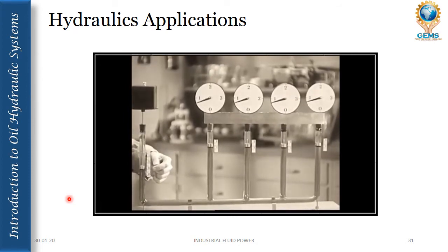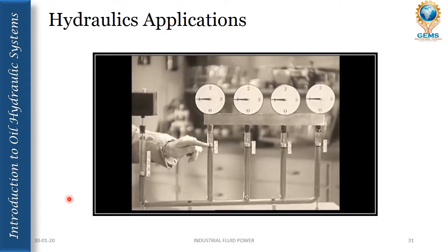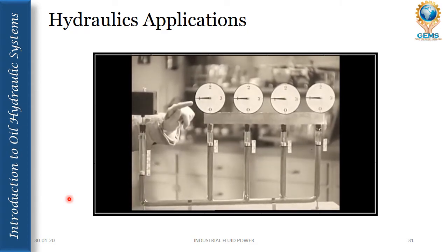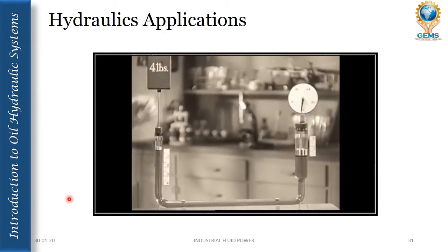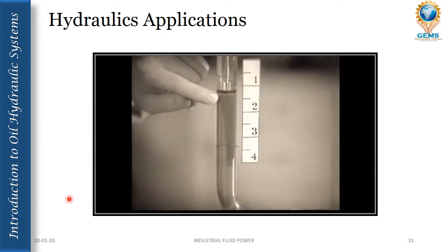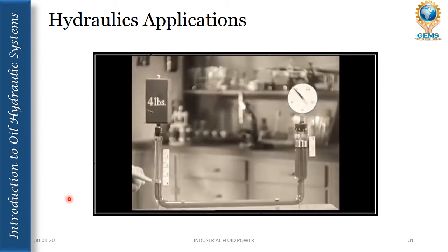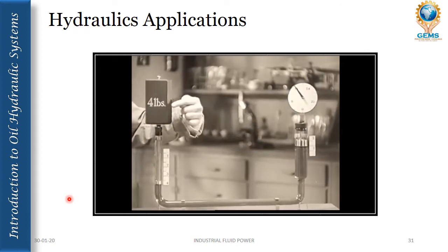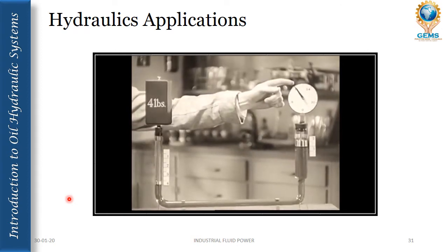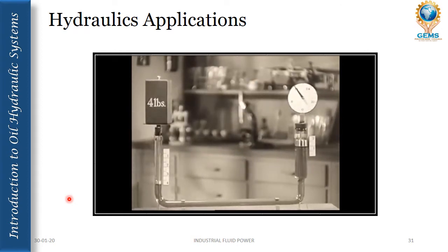Now, when the single piston travels 4 inches, each of the 4 at the other end travels 1 inch. A large piston of the same area behaves the same as 4 smaller pistons. Moving the small piston down 4 inches carries the large piston up only 1 inch, but with 4 times the force applied. This is the principle on which commercial and industrial hydraulic systems are based.